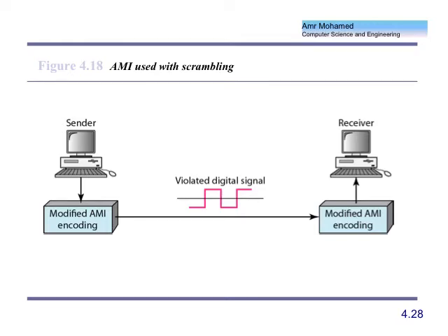So next time we talked about block coding, and we said that the purpose of block coding is two things, right? To enhance error detection and to enhance the self-synchronization issue. And we have seen that combining block coding with a line coding scheme like NRZ with inversion can save some bandwidth compared to, for example, the biphase line coding scheme.